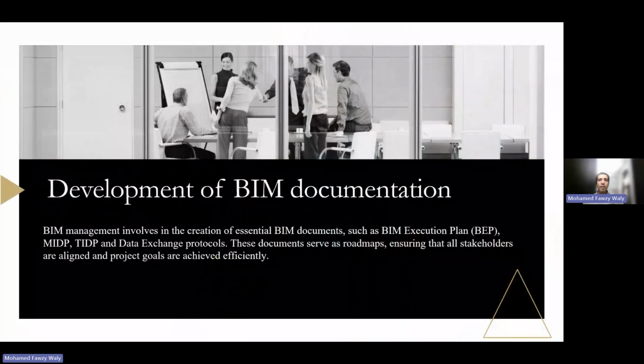If we talk about the development of the documentation, this is one of the main tasks and the main important responsibilities in the BIM management role. There are a lot of data and documents that should be prepared and shared within the BIM people in the project, like the BEP, the MIDP, the TIDP, and for sure mainly the data exchange protocols, as these documents are the roadmaps that ensure that all stakeholders are aligned, and the project goals are achieved efficiently.